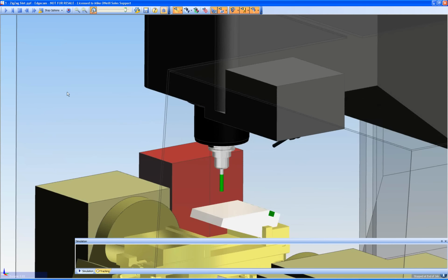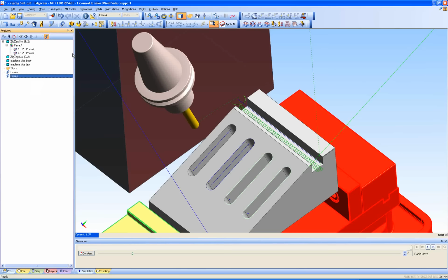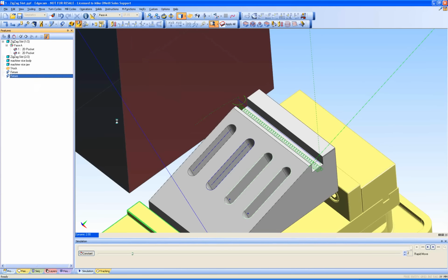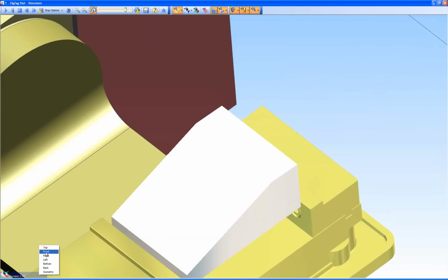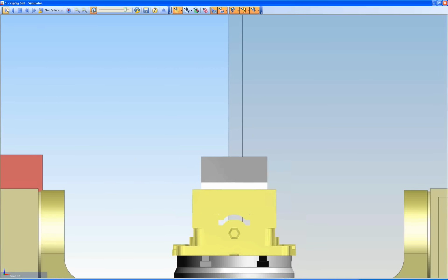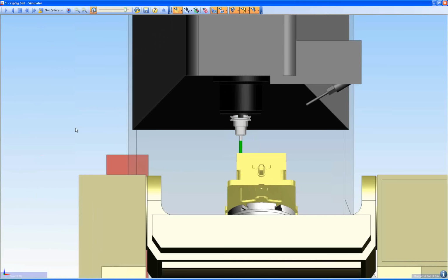So it can save many a frustrated couple of moments if we know that little problem, secondary rotary axis. So take it back to the simulator. Obviously all will be well here. You just swing round into the front again, and if I'm stood at the front of this trunnion type machine tool, you'll now notice how it's indexed away from me, so I can't actually see the component.